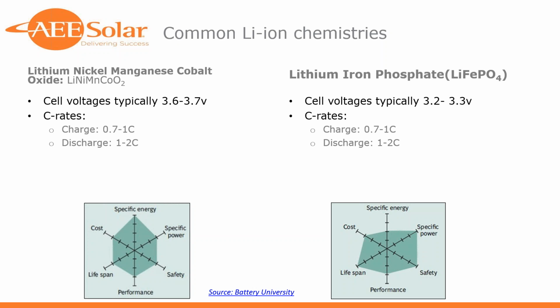Both of these chemistries are going to be similar in cost. And this information is from, I think, last year. So cost is always relative, of course, and it's going to vary by manufacturer, by application, by power rating, by scale, etc. On the other side, lithium iron phosphate, where does that have a relative advantage over nickel, manganese, cobalt? Specific power. So again, the power in terms of wattage or amperage you're going to be able to pull out of a specific mass. Lifespan: you're probably going to get a few more watt hours through that battery over its lifespan. And safety.